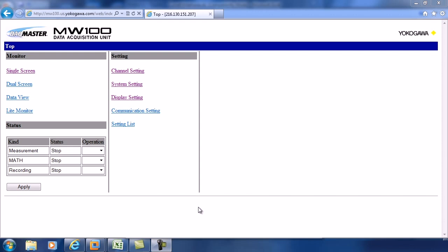It also can do a nice function called math channels, which allows you to take sensor input and correct for real-time stuff like pressures and temperatures. In this case, it allows us to enter our correction function, so we can take in our percent methane from the sensor and automatically generate the correction factor. So let's take a look at it.